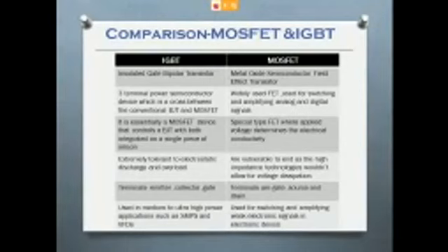It controls electrical conductivity. IGBT is extremely tolerant to electrostatic discharge and overload, which is why it's being used for high power devices, and MOSFET on the other end is vulnerable, as the high impedance technology wouldn't allow voltage dissipation. Of course, that's why it is being used for low power devices. IGBT is a three-terminal device, as I've said before.